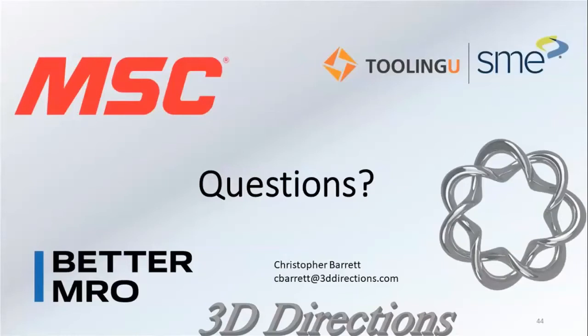The process is very reliable after first trials. It is. That's one of the reasons why a major OEM will give you a specific build file with a specific pattern and say use this machine. Because they have to certify quality control. The egregious failures I showed you, most of those were trying to cut corners with supports or were just teaching people to mount things. If you want a really reliable part, use a lot of solid supports. You're going to have to get them all back off, but your part's not going to warp on you at all. It's going to lock in.